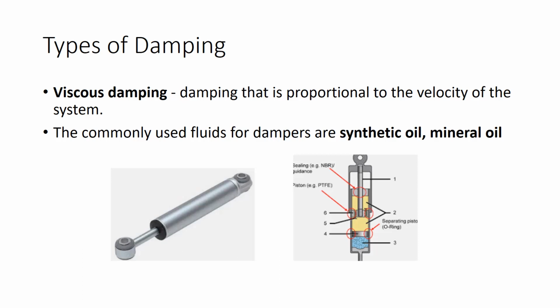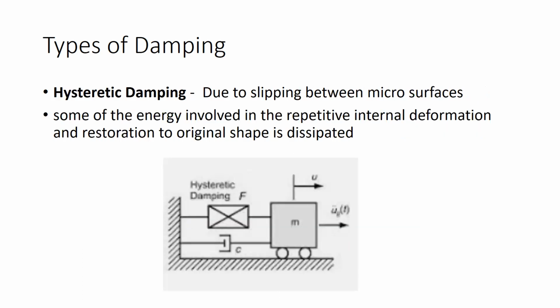Damping of the oscillation amplitude increases with the increase of the frequency and is inversely proportional to the viscosity of the fluid. In contrast, the penetration depth decreases with the increasing frequency and is directly proportional to the viscosity of the fluid.